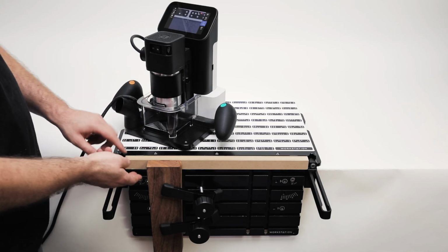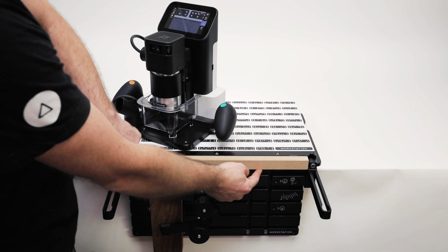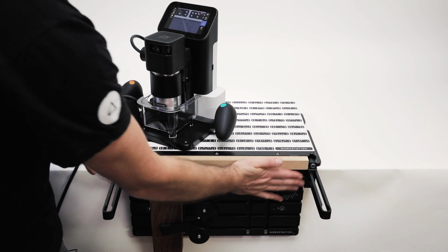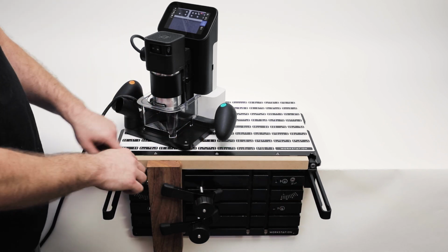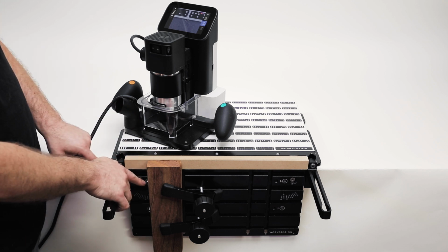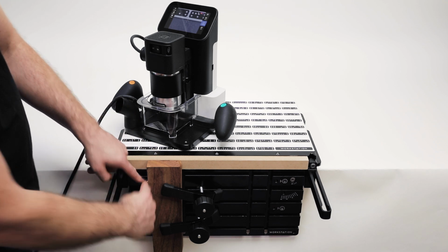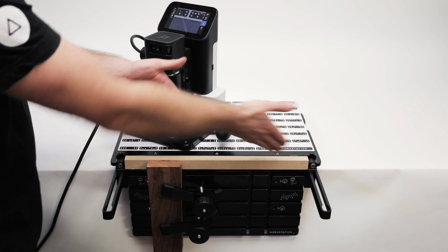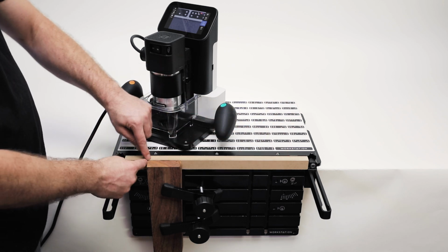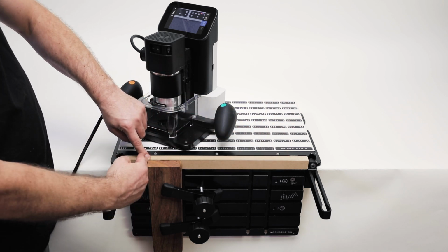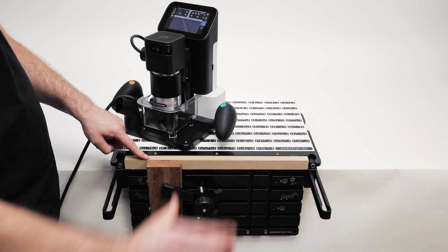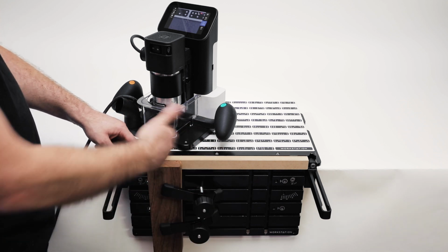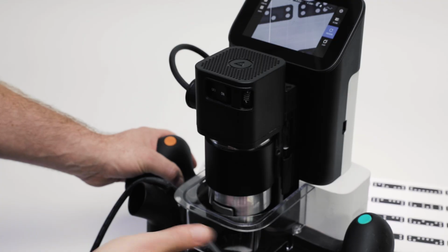Another big performance boost that you get with the workstation is built into the fact that we always index into these same locations with the vertical alignment pins and machined front face of the workstation itself. So you can raise it up and actually grid against the workstation itself. And you can do that once. Then you don't need to rescan when you add stock that indexes against that face and the pins.